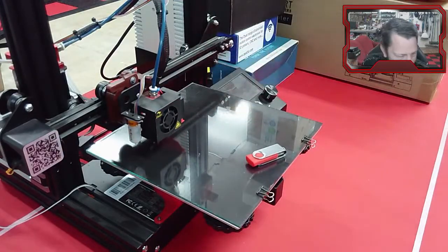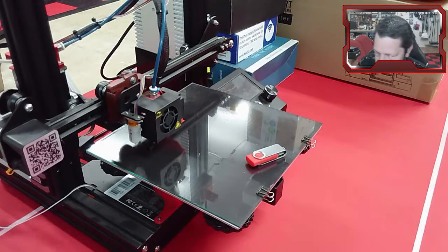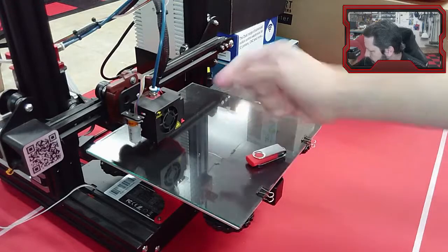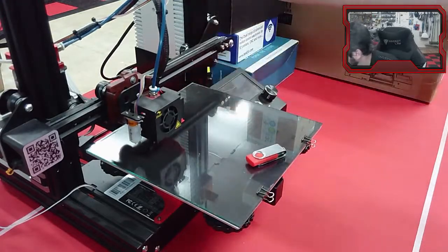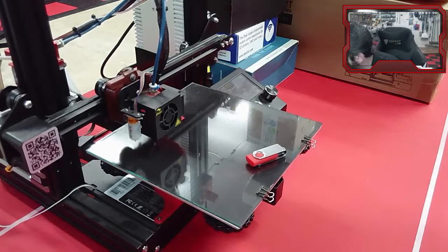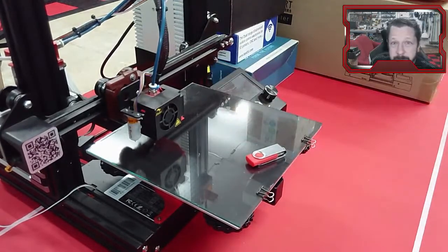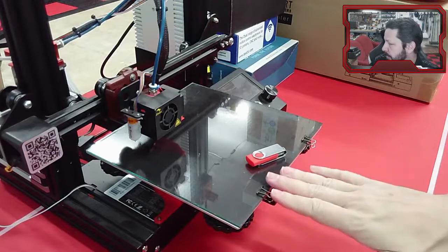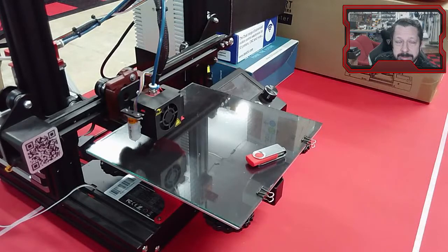I actually don't have anything 3D printed in front of me right now to show you, but it'll print it out one layer. This whole gantry will move up, print another layer, move up, print another layer, move up again, print another layer. Those layers can be really thin. Even on this machine, those layers can be 1/10 of a millimeter, but typically that's a little bit thin for what I normally print, just because it takes so long to build something up when you're going that thin.